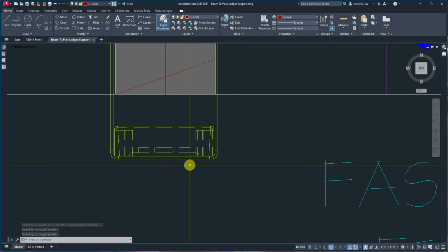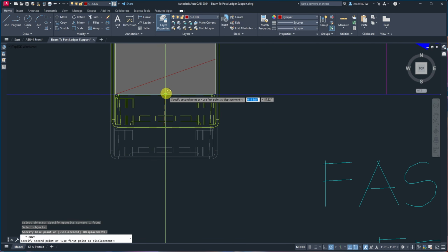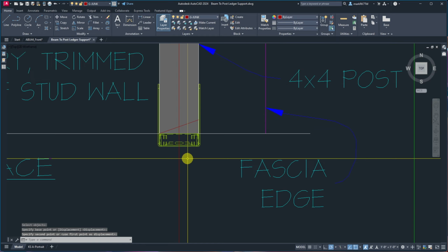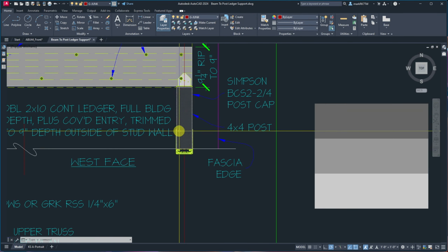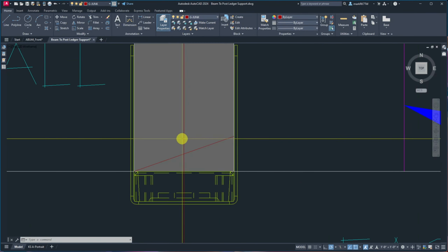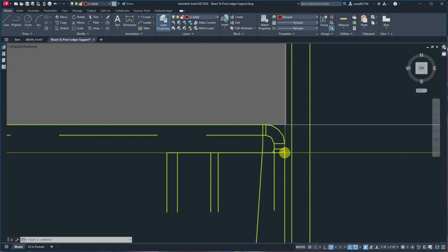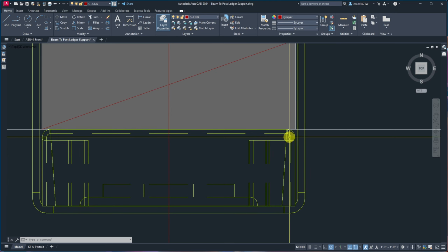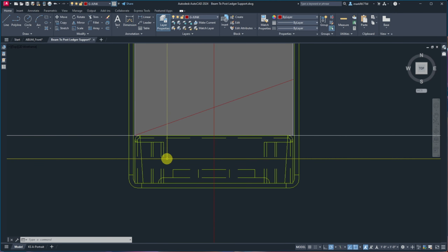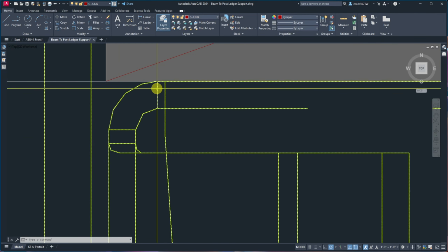Now I can move this from that to the intersection there, and it is squared up, center, ready to go. Way too high. This is for a different type of detail. I'm just showing how I would use it. I also would come in here and I'd clean this up. There's too much line work. It's a pretty far out detail. I don't need all of this. So I'd probably take all these little lines, those out, trim that back a little bit, get rid of that